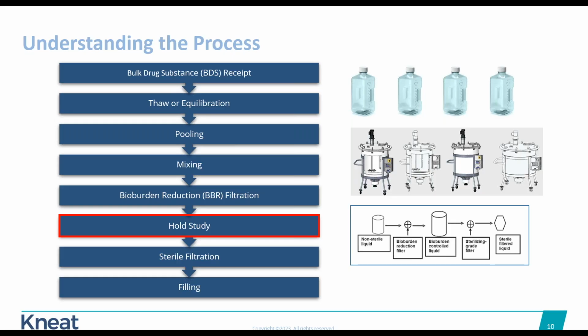The filling machine is very, very high tech. There's a lot of robots going on in there. So sometimes if something goes wrong, it takes a little bit of time to fix it. So that's why I did see the hold study oftentimes placed here. Also, you might be wondering why this isn't after sterile filtration. And that is because the FDA does not suggest to do a hold study after the last leg of filtration.